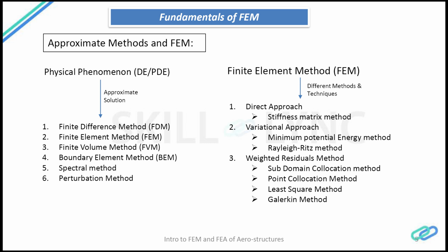To put it in much simpler terms, imagine a structure, imagine a cantilever beam that is being modeled in your software. The cantilever beam can be broken down into smaller elements, say 1D elements or 2D elements. Based on the type of element you select, the polynomial equation is formed.